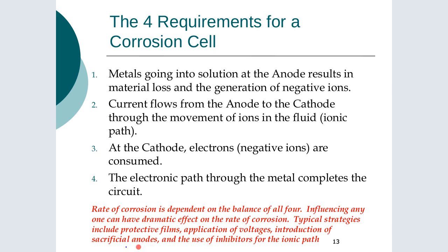That's a nice one that is used in galvanic corrosion. So you put in a material that forms a new anode, something that takes up the role of an anode. You put that in, and that has no function other than to be eaten away. And you know it's going to be eaten away, and you're happy with that. It has no structural function, for example.